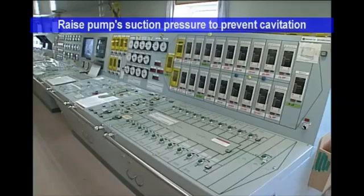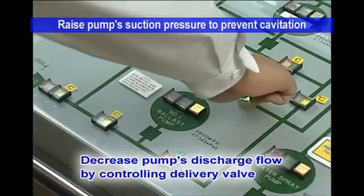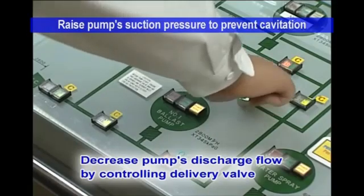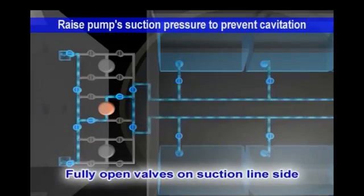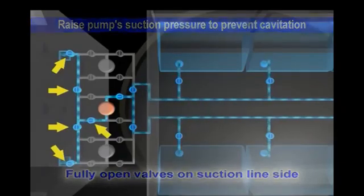To prevent cavitation, raise the pump's suction pressure. In terms of pump operation, decrease the pump's discharge flow by reducing the discharge valve opening. To raise the suction pressure, decrease the suction line resistance. With some ships, suction line resistance is decreased by keeping valves on the suction line side fully open at all times. Their opening is not reduced.